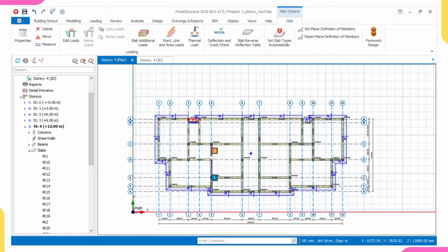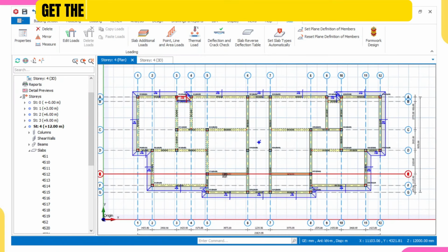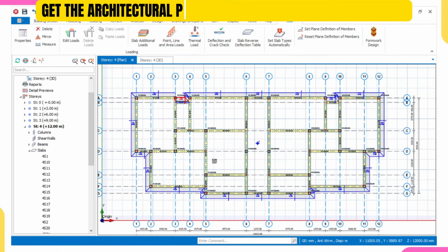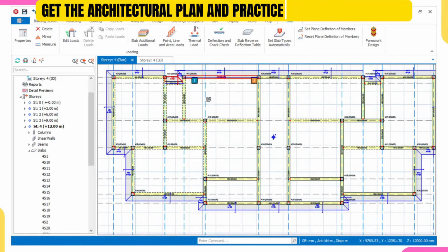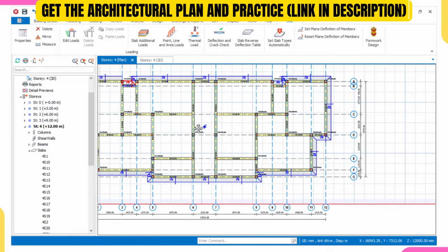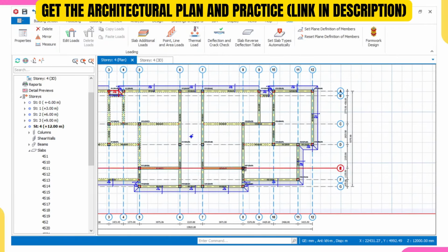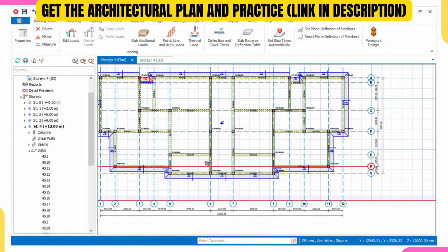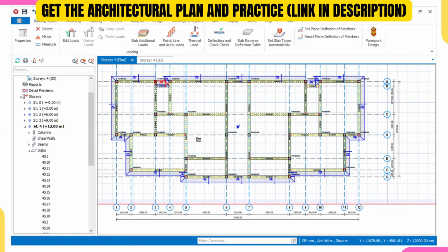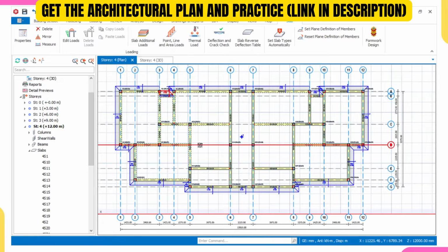Then next thing you do, you can come and delete some of this beam, because this is the last floor. And two, we'll be having our crosses running across this beam. So any beam that you feel is not really necessary, you can delete it, to save cost. But my own, I don't think I'll be deleting any. I'll just leave it like this.